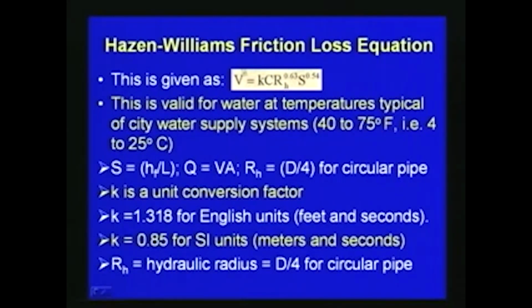So, depending upon the relative roughness the friction factor changes, and as the friction factor changes the head loss also changes. All these important aspects we have to consider in the design of pipe flow systems, while considering a typical system. Now, one of the most commonly used equations for pipe design, other than the Colebrook equation with the friction factors obtained by Colebrook, is the Hazen-Williams equation.